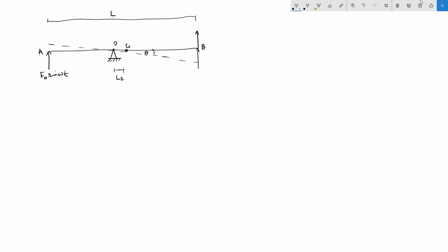I've drawn the free-body diagram with the sinusoidal force at A over here, and then I've got two forces at this end. One of them will be the component from the spring and the other will be the component from the viscous damper. So we need to look at the force component that's going to be provided by the spring.